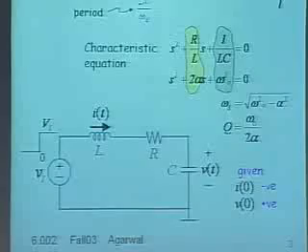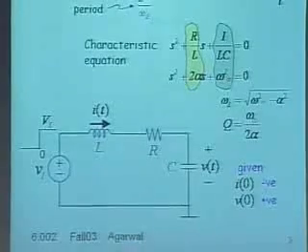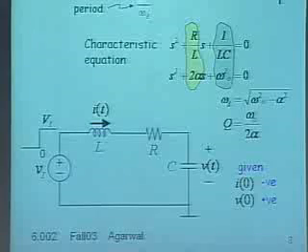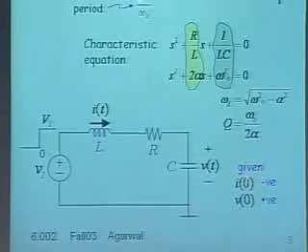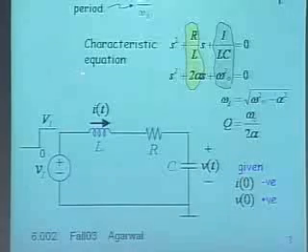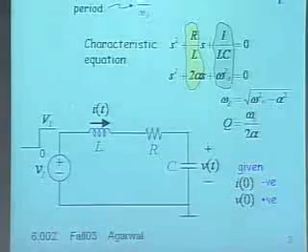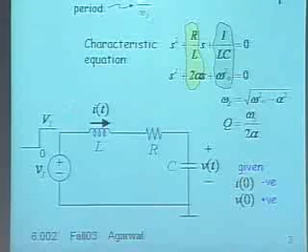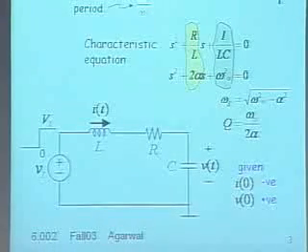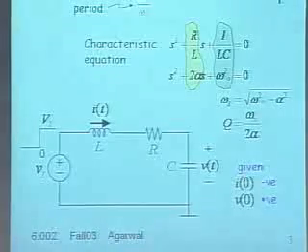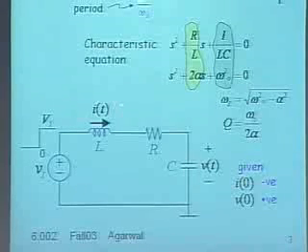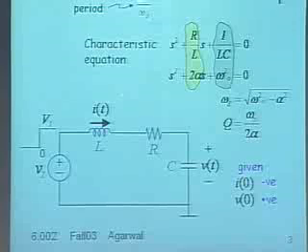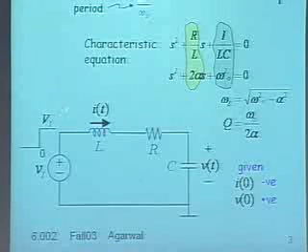Now, I want to find out, at time t equals 0 plus, in which direction does the capacitor voltage go, increase or decrease? Let me take a look at the inductor current. I'm told that the inductor current is negative, which means the inductor current is going in this direction initially. Now remember, just as the capacitor is one stubborn nut trying to hold its voltage, the inductor is just as stubborn. It's trying to maintain its current, and its initial current I0 is in this direction.